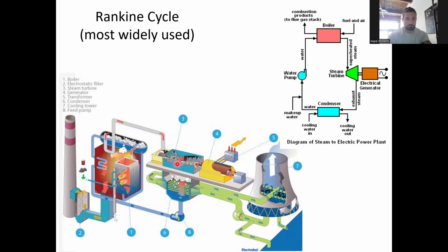And then the turbine is going to rotate, and the steam is going to be expanded through these turbines, which rotates the generator that's going to produce electricity, and then the low temperature, low pressure steam is condensed by water that's coming from a nearby lake, and then the water vapor from that absorbing that heat can be released to the environment.